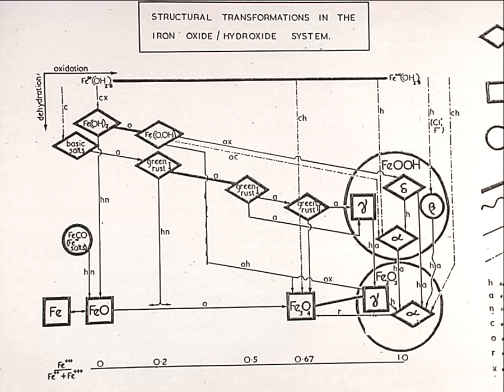And you not only end up with a range of oxides: Fe3O4 magnetite we've talked about, and Fe2O3, which is our common rust, is almost all iron 3. But you then also, depending on the pH, end up with a range of oxyhydroxides and hydroxides, which are the sort of next stage of the hydration of the oxides, and you get different colours, which is quite useful as well for identification purposes.